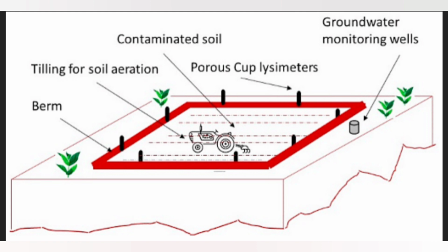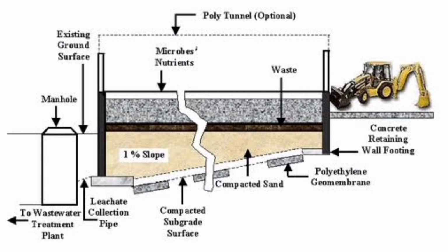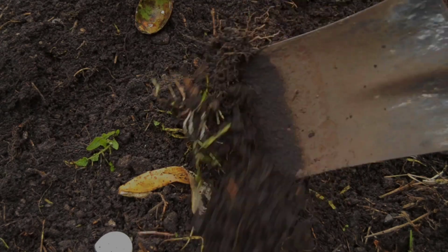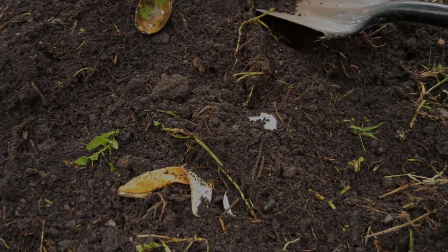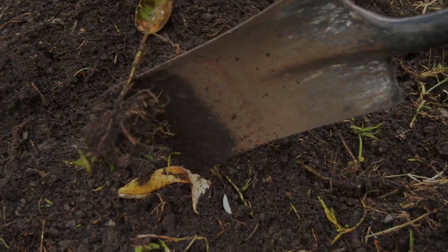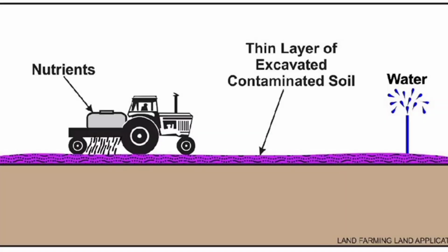Land farming. Land farming is the most basic method of bioremediation. Contaminated soils are blended with soil amendments like bulking agents and fertilizers before being tilled into the ground. They are excavated and spread out in layers of around 0.3 meters thickness on a lined treatment area in land farming. Periodic flipping of the bed and the addition of nutrients can help with bioremediation. Microbiological and oxidative mechanisms degrade, convert, and immobilize contaminants.